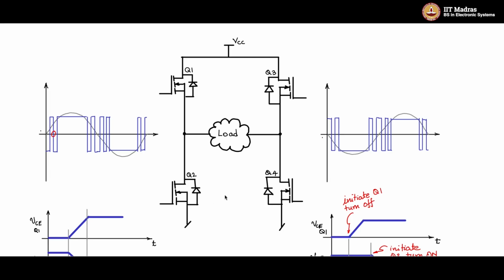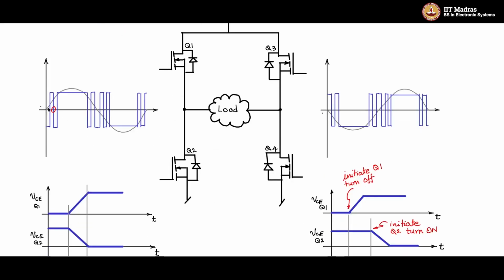In the literature, you will see that I will clip this, take only the positive signals and give that to the gate drive of Q1, and I will invert that and give it to the gate drive of Q2. That's how the literature will show in the circuit diagrams. That will not be a practical solution because of the shoot through problems. You have to give a conscious dead time. So I will introduce in between a dead time circuit, and we will discuss how to do that.